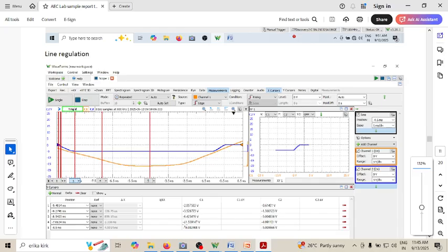So it requires minus 6.7 or less to get minus 5 volt. Can you see it's minus 5, minus 5, minus 5? So the input voltage has to be lower than minus 6. That means minus 6, minus 6.4, minus 11, minus 16. For all those voltages, you are getting minus 5 volts.